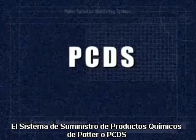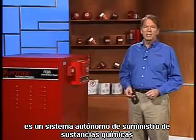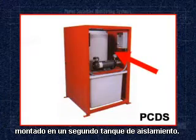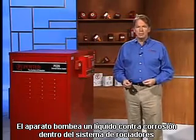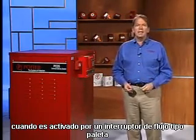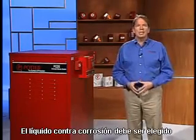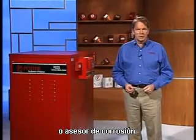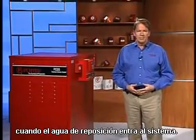The Potter Chemical Delivery System, PCDS, is a self-contained chemical delivery system designed for wet pipe systems. The chemical is contained in a polyethylene primary tank mounted in a secondary containment tank. The unit pumps a corrosion-inhibiting fluid into the sprinkler system when activated by a dedicated vane-type flow switch installed on the system riser. This corrosion-inhibiting fluid must be chosen by your fire protection engineer or corrosion consultant. The pump delivers the chemical as makeup water enters the system.